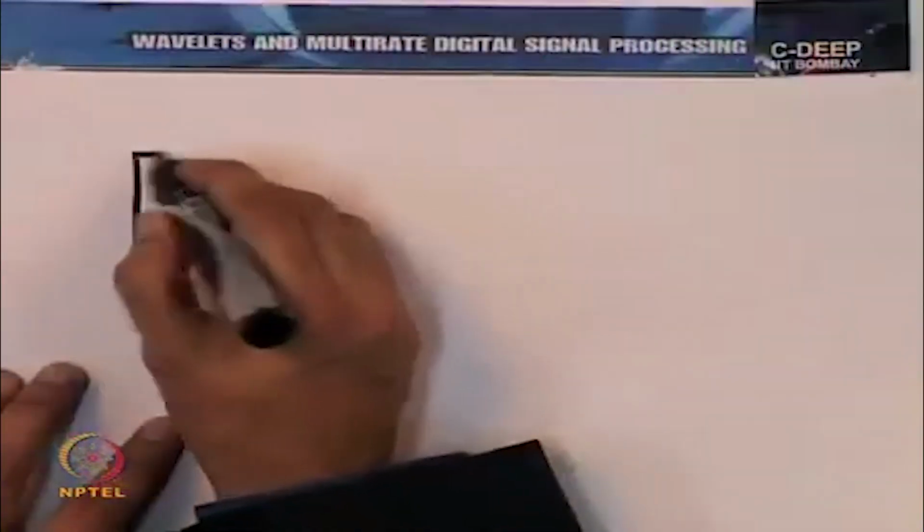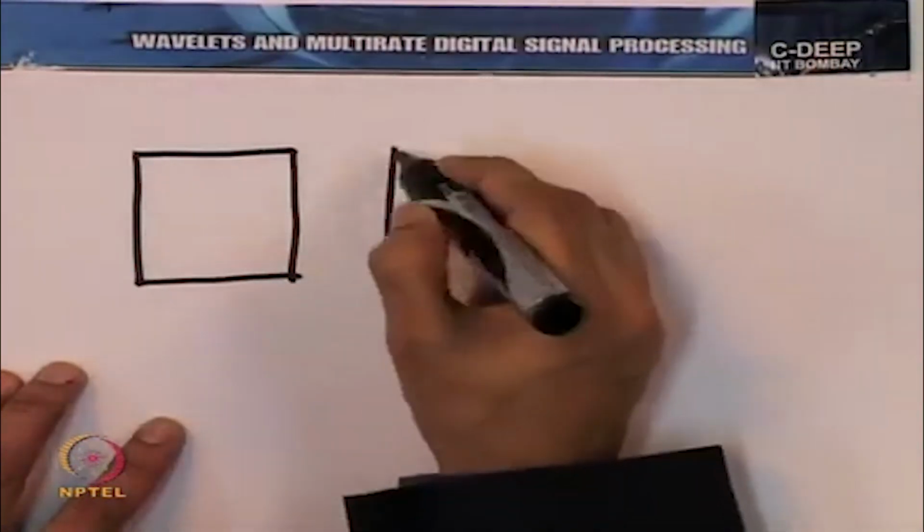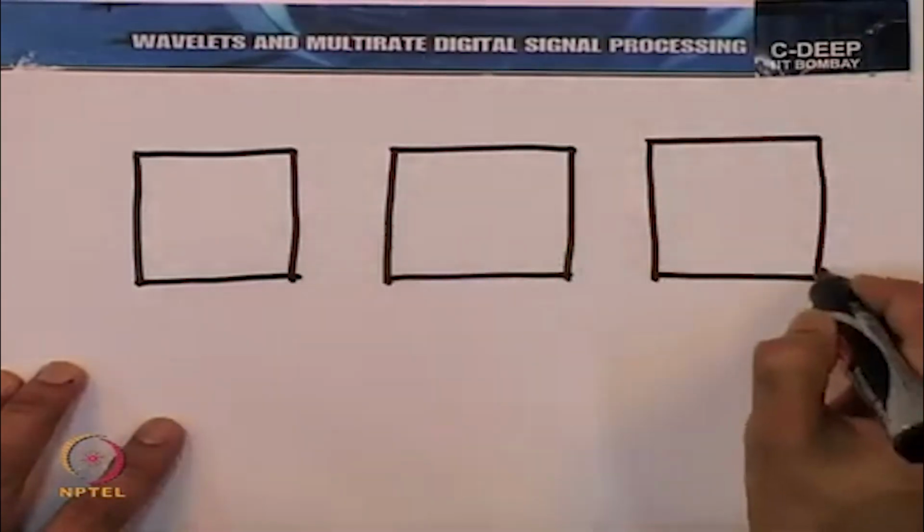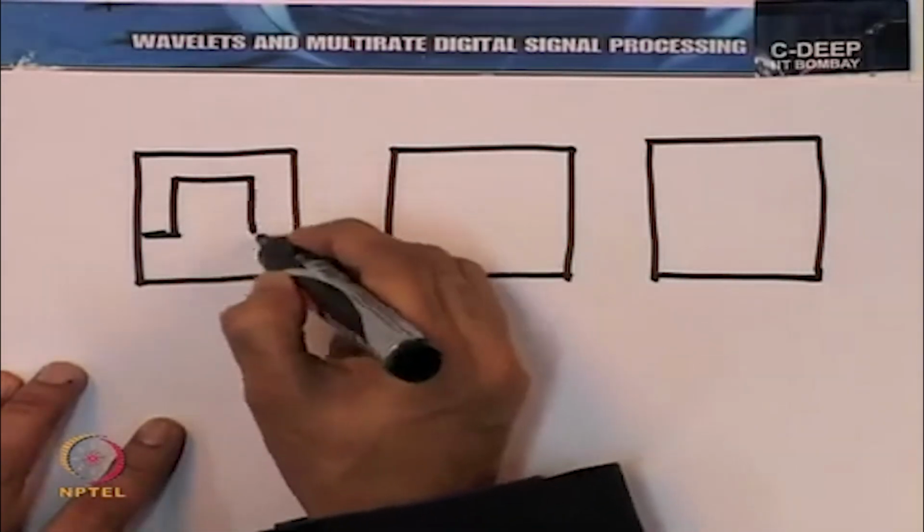In fact, one way of going closer is to repeatedly convolve the pulse with itself. So, if you took this sample and whole system, and if you made a cascade of one more such system with it, you get the triangular pulse. Now, if you take a cascade of 3 such systems, put one more in cascade. What I mean by that is, take this cascade. So, I have a cascade of 3 LSI systems, each of whose impulse response is essentially a pulse.